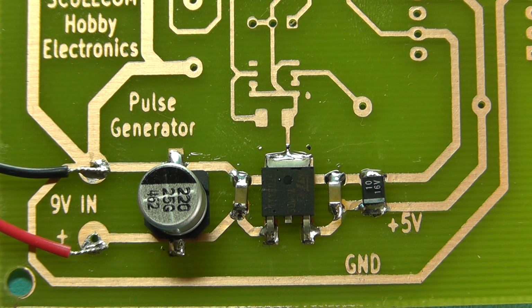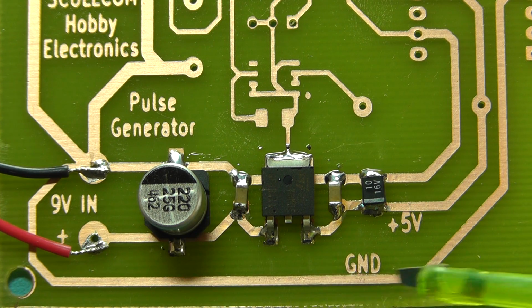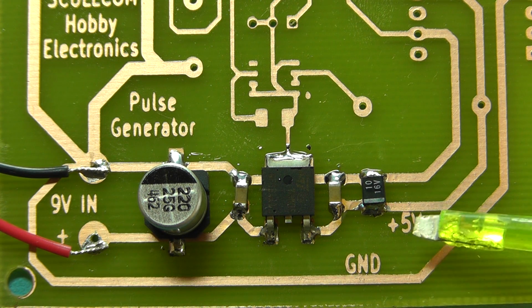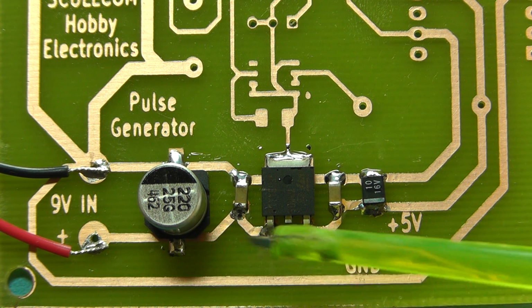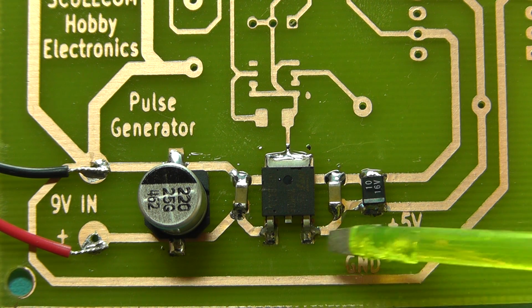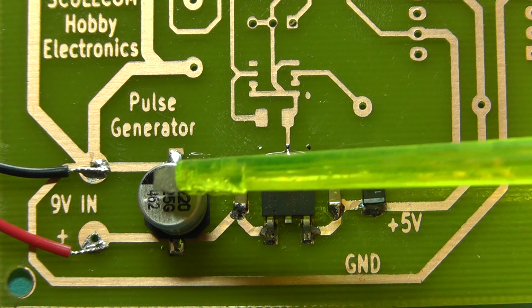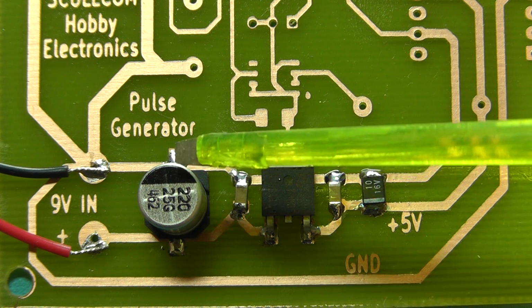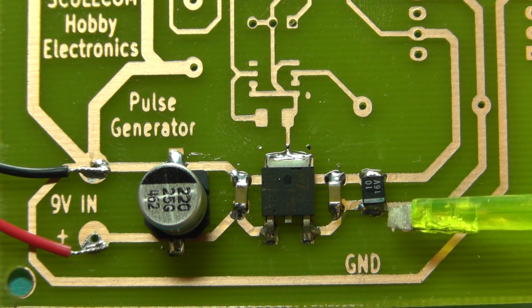Here we see now I've mounted the components for the power supply area of the board, and I've just quickly tested that, and we've got 5 volts coming out, so that's working fine. I'll just point out a couple of things here. Mounting the surface mount capacitors there, no issue with the 100 nanofarad capacitors because there's no polarity on those, but on the electrolytic there, the black band on that side is the negative side of the electrolytic, and on the tantalum capacitor there, the 10 microfarad, you'll see that there's a stripe which indicates the positive side of the tantalum capacitor.